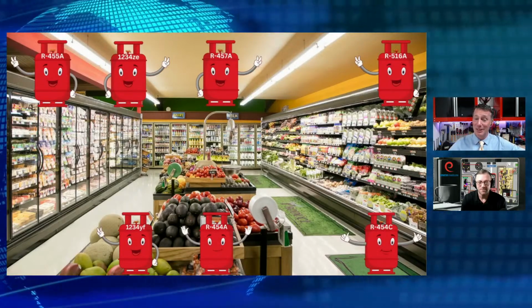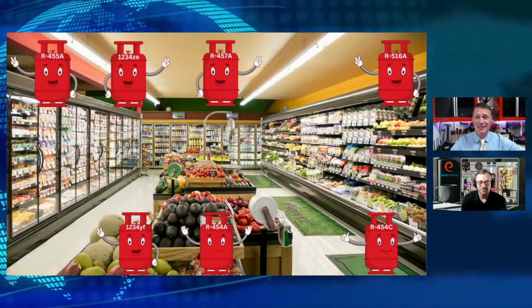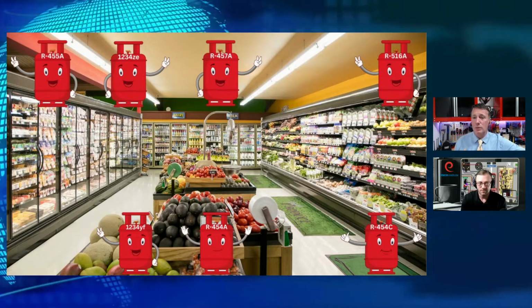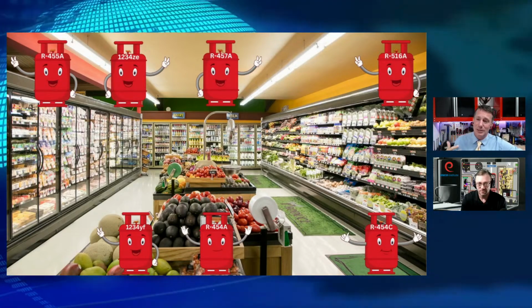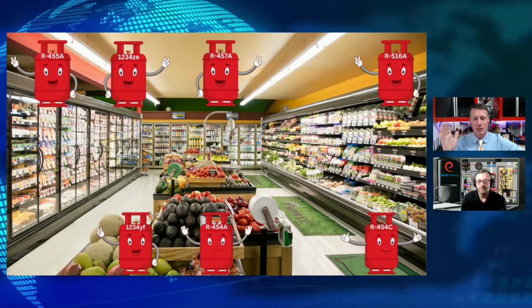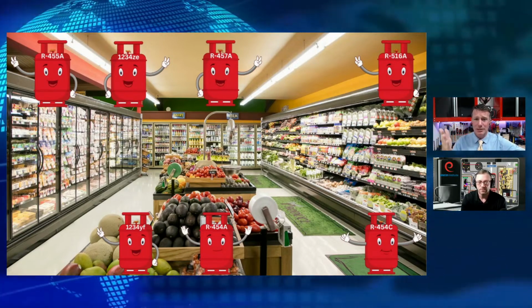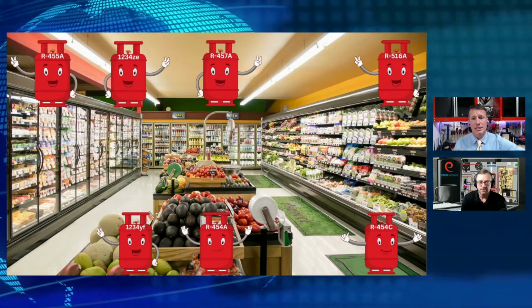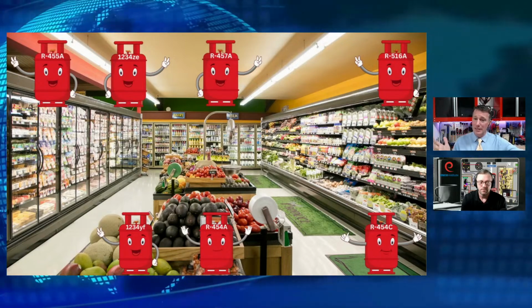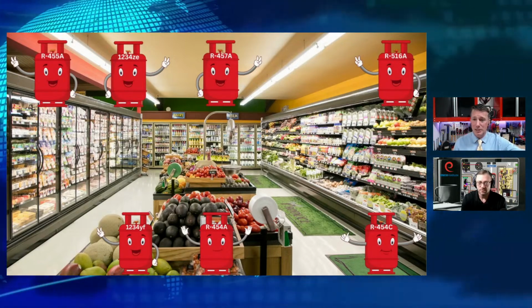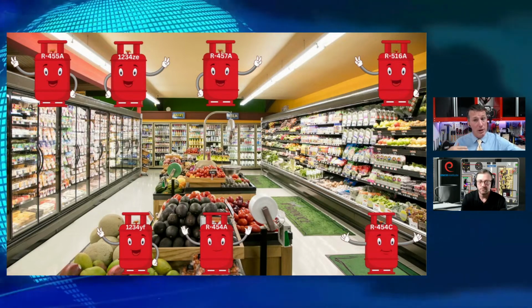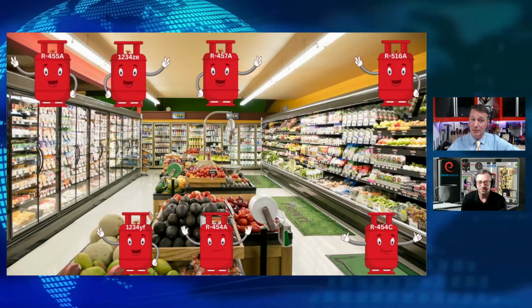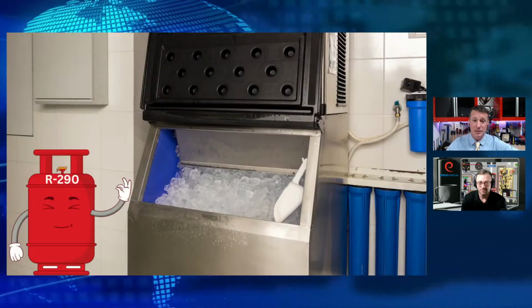Yeah, this is a little familiar to me, right? If you're a grocery store technician, you're used to seeing some refrigeration racks. Well, things are going to change a little bit for you as well when we start talking about new installations. We've already seen CO2 systems out there, but we're also going to see new equipment utilizing 1234YF remote condenser systems. 1234YF, we will still see that, 454A, 454C, 1234ZE, right? So we're seeing a variety of refrigerants that could be used in these applications by the manufacturers. So your 404 is going away, and these are going to be some of the replacements that you see for that. And like I said, very short period of time. We're not talking about 10 years down the road. We're talking within the next year, year and a half.